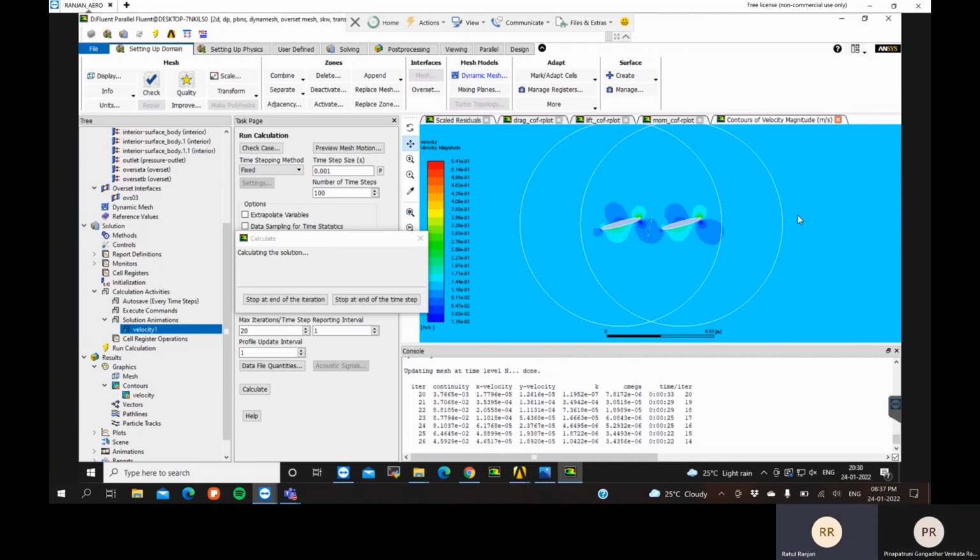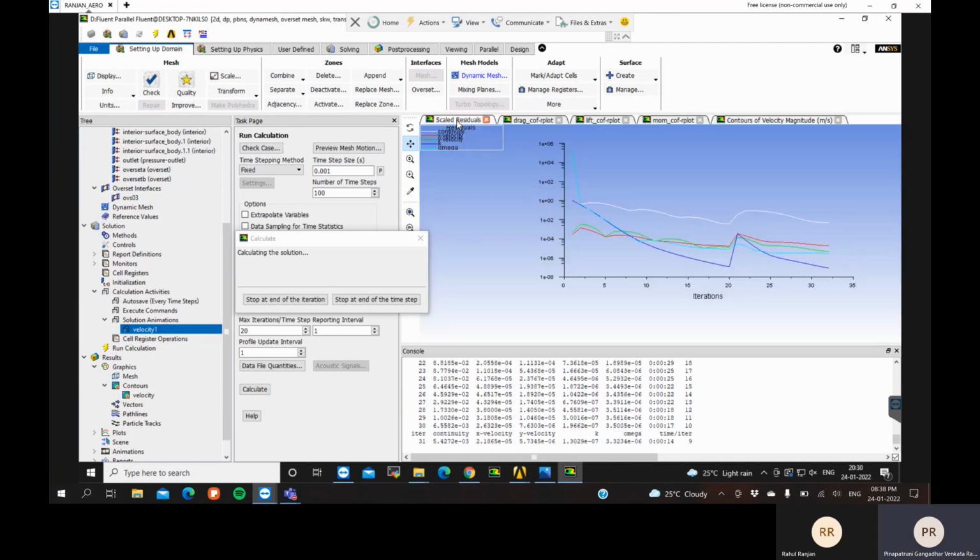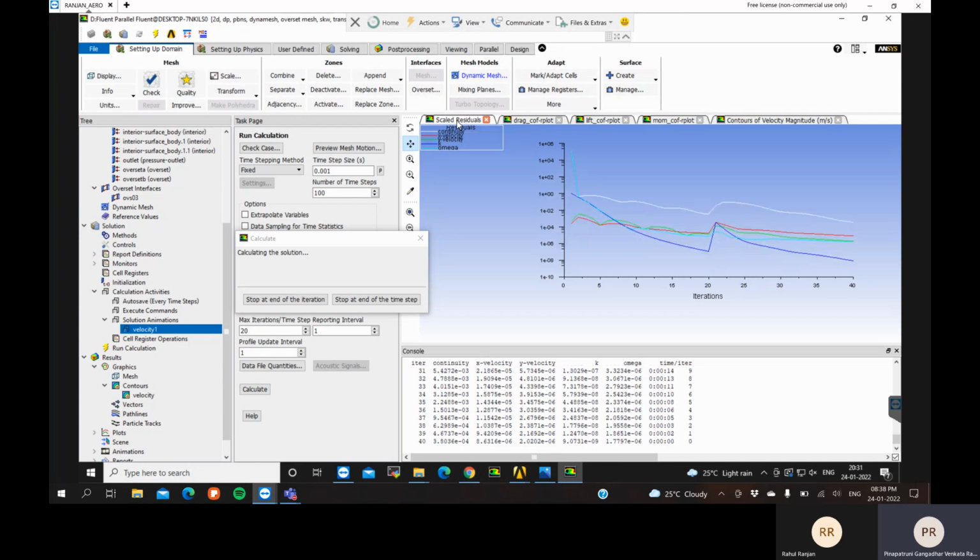It looks good right now, but convergence is the issue. If no convergence is there, something will happen at some point. And our orthogonality, if you see, is 0.04. It is not okay, because at those locations there is a chance of getting divergence or large values in numericals.